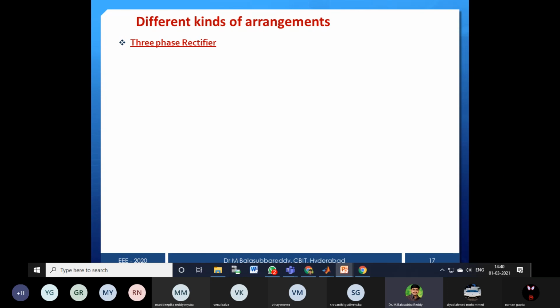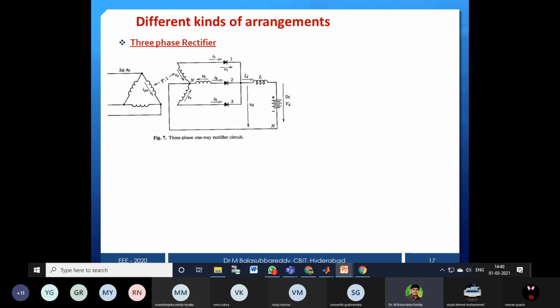The three-phase rectifier is another configuration, because what we discussed so far were different configurations, and the problems and valve voltage ratings all differ. Practically, in HVDC transmission and so on, three-phase rectifiers are used. In this three-phase rectifier, our only intention is to conduct the devices under forward bias condition. If it is a diode, we don't require any firing pulse.